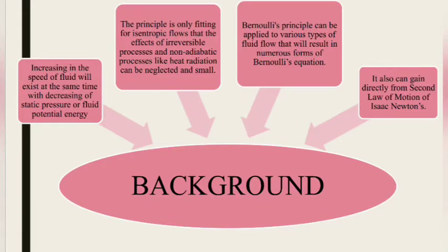Bernoulli's principle can be applied to various types of fluid flow that result in numerous forms of Bernoulli's equation. The simple form of Bernoulli's equation is valid for incompressible flows, for example most liquid flows and gases moving at low Mach number. At higher Mach numbers, more advanced forms are applied to compressible flows. Bernoulli's principle can be derived from the principle of conservation of energy. Lastly, Bernoulli's principle can also be gained directly from Isaac Newton's second law of motion.